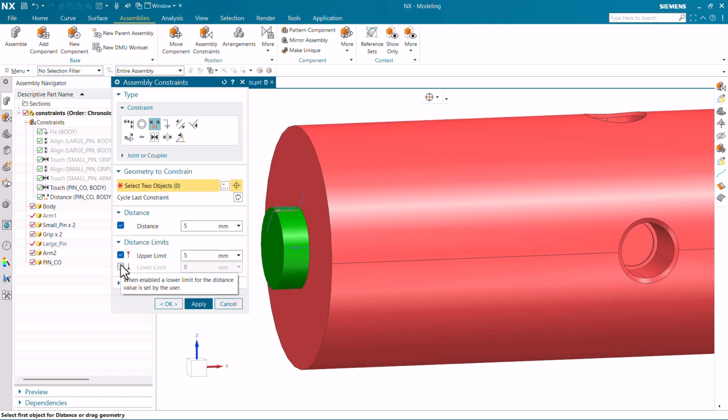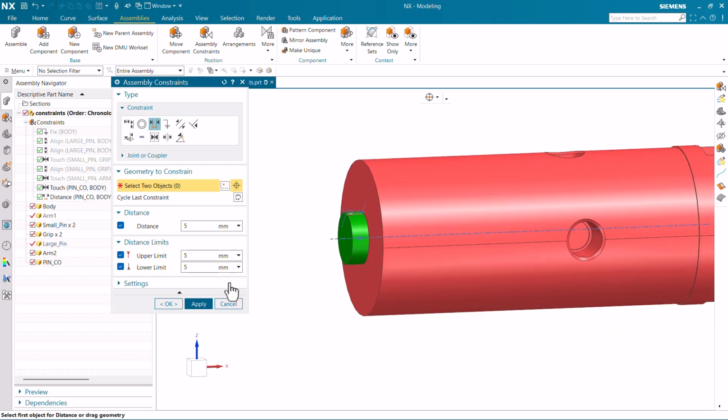This is going to be the upper limit and this is going to be the lower limit. Upper limit means the maximum distance which it can cover. So it is going to be 15, and okay, just give it some more. And this is going to be 10. Okay, now why have I given the 10? Here you can see the alert. The distance value is less than the lower limit of 10 mm. Now you can clearly see that the lower limit is 10.